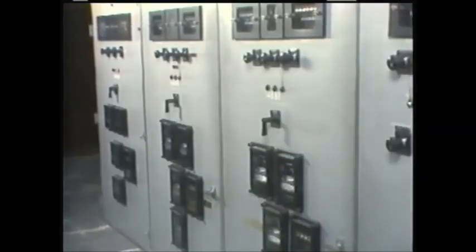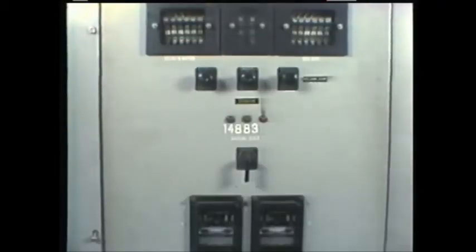Circuit breakers and fuses are just two of the many protective devices used in distribution systems. In the next part of the program, we'll look at some other types of protective devices. But before we leave the topic of circuit breakers and fuses, let's review some of the points we've covered. We said that circuit breakers are basically automatic switches that can interrupt the flow of electricity through a distribution feeder. Circuit breakers have the capability of opening and closing automatically, and when used as part of a coordinated protection system, they can operate in a number of different modes.